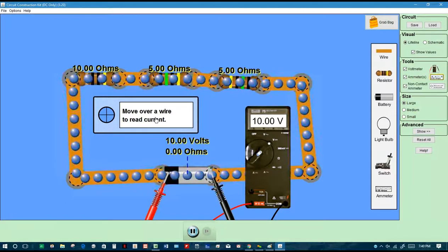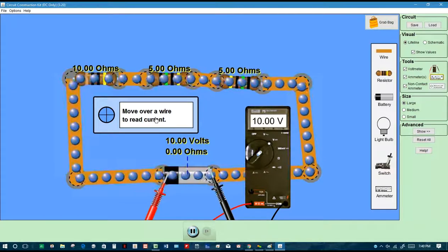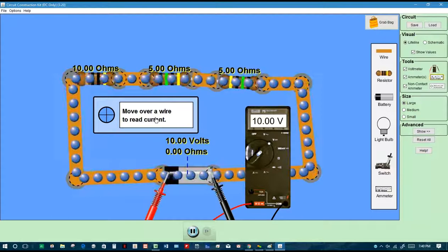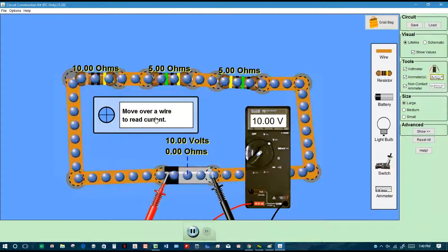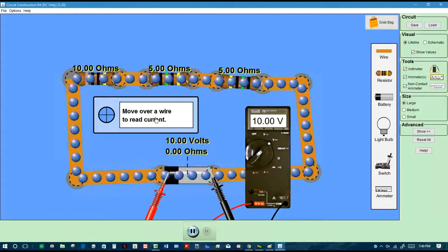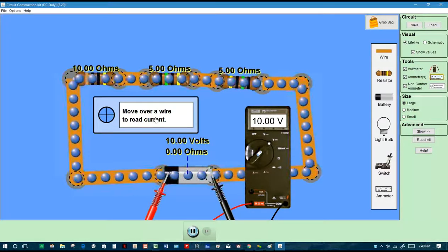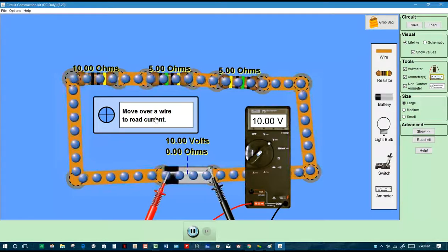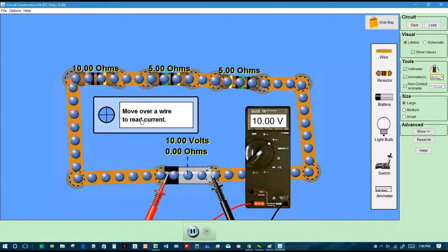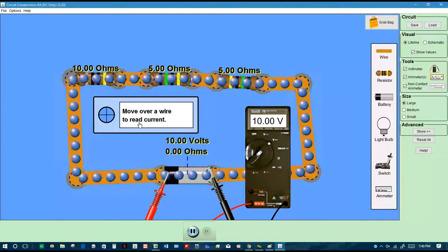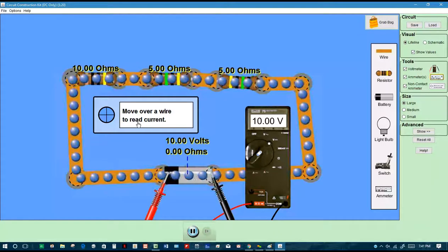20. It's 10 plus 5 plus 5, right? So what is the total current going to be? So the total resistance is 10 plus 5 plus 5, which is 20 ohms. The last one I added in there was a 10 ohm resistor, and then we've got a 5 and a 5. So we have a total resistance of 20 ohms. The battery is still 10 volts, so what should our current be now? Still 1 amp like it was before with just the two 5 ohm resistors, or more than 1 amp or less than 1 amp now that I added a 10 ohm resistor?